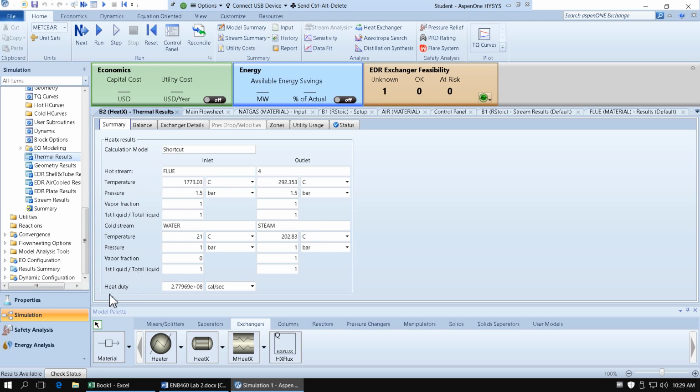And you also get this heat duty for the whole heat exchanger. And that will be important in sizing your heat exchanger. So just choose megawatts, as specified in the instructions, and it's 1163.8. So you have to get a boiler with a heat duty of 1163.8.